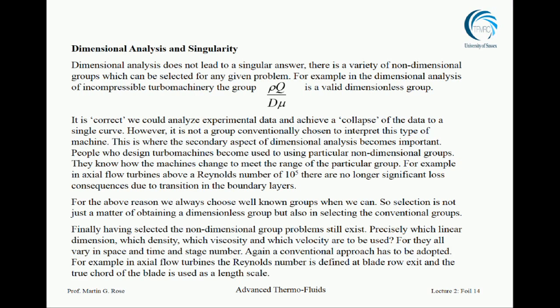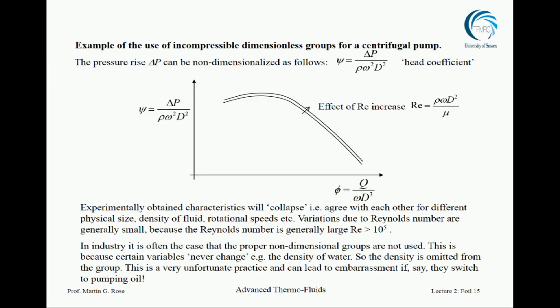Now, back in the pump industry, when we test a pump, this is one of the graphs that we produce. This is the flow coefficient you should recognize from the dimensionless analysis of incompressible machines that I've just shown you. That is the dimensionless head rise, known as the head coefficient. In the pump industry, we don't talk about pressure, we talk about head. Head is how high the water is, the head of water, and of course the head relates to the pressure through rho g h. So it's just terminology, but in the pump industry it's called head.